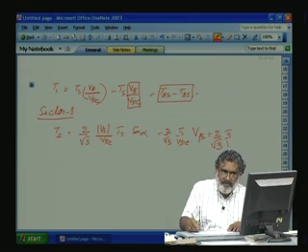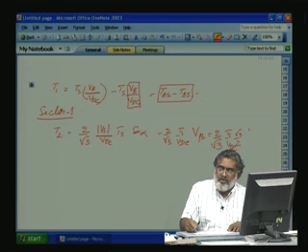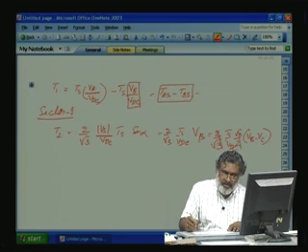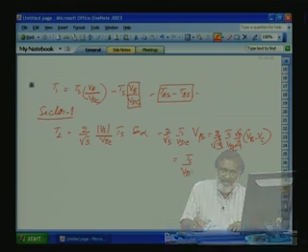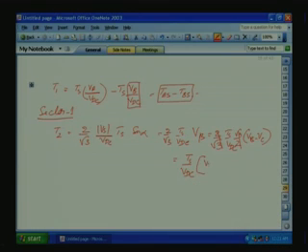That is equal to 2 by root 3 into Ts by Vdc. What is V beta? V beta is equal to again root 3 by 2 into Vb minus Vc. So this root 3 by 2 and 2 by root 3 go away, and this will be equal to Ts by Vdc into Vb minus Vc. This, in the fictitious time, we can write as Tbs minus Tcs.